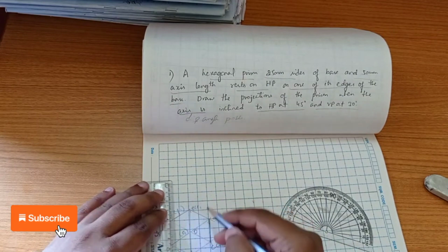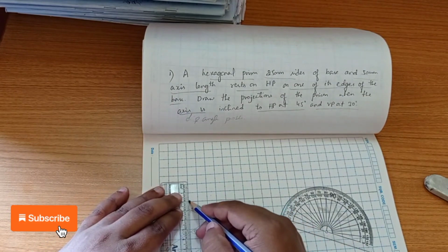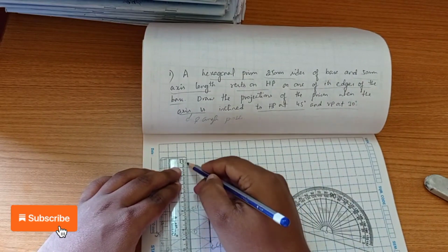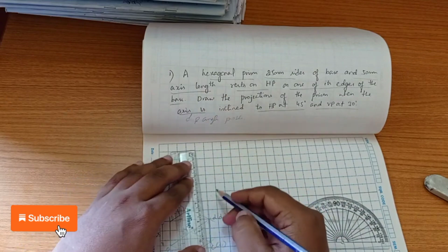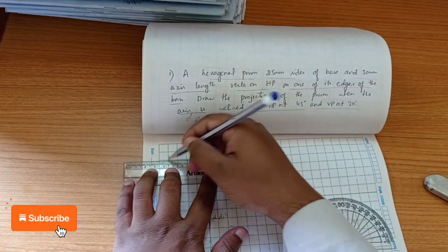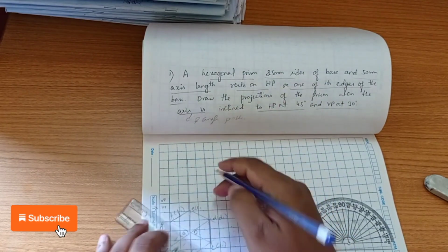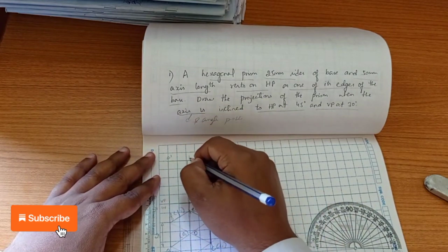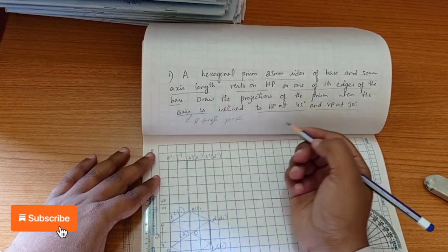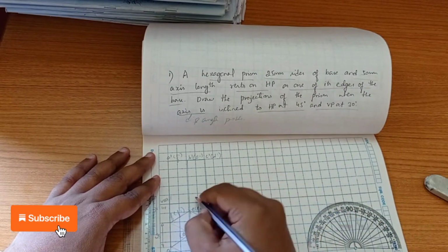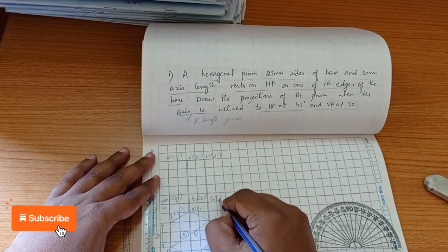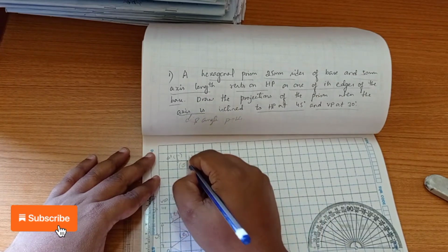Okay, now projecting this. So axis length is 50. So for the top face notations we'll write A dash, B dash, C dash, this is F dash, E dash and D dash not visible. Okay, similarly A1 dash visible, B1 dash visible, C1 dash visible, but F1 dash, E1 dash, D1 dash not visible, O1 dash, O dash also not visible.